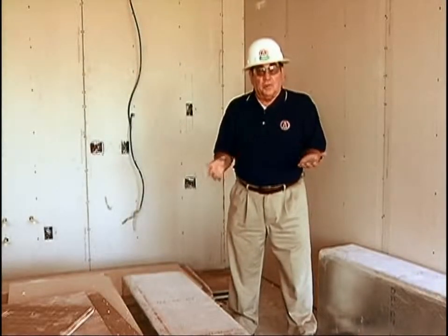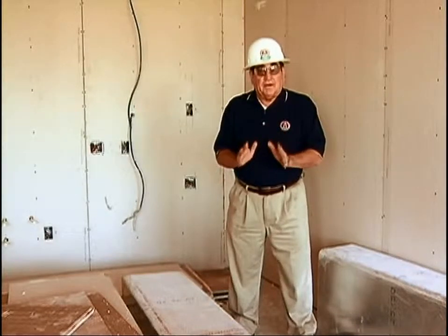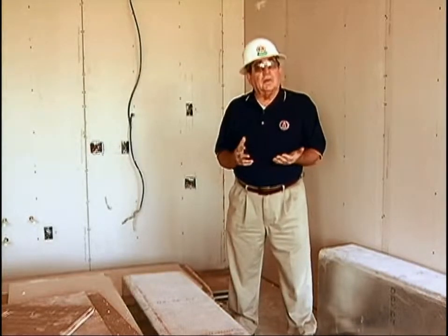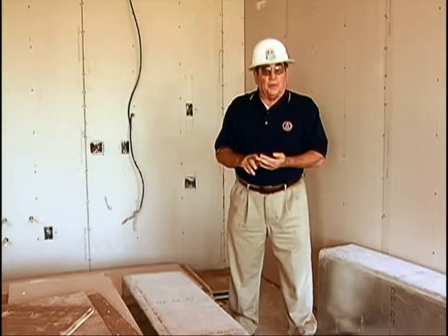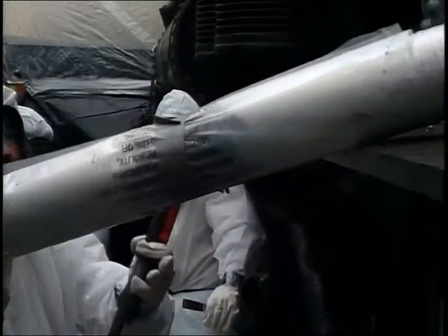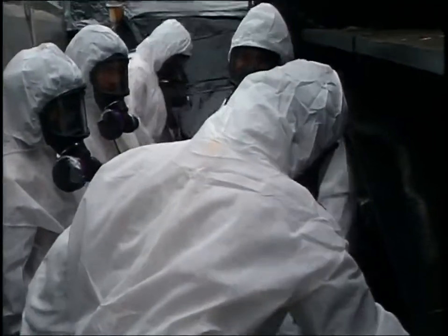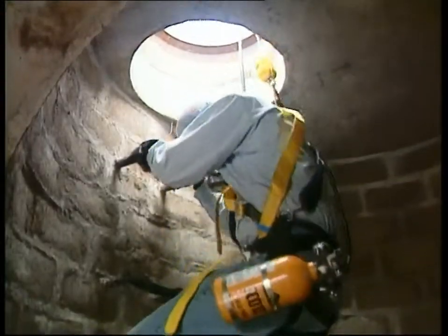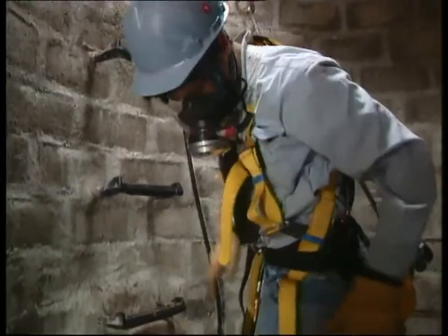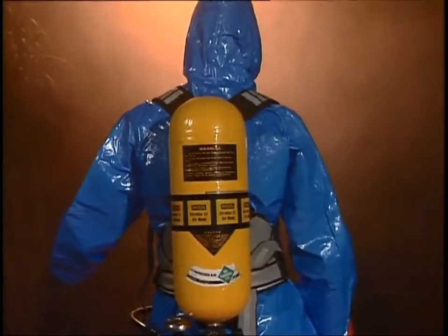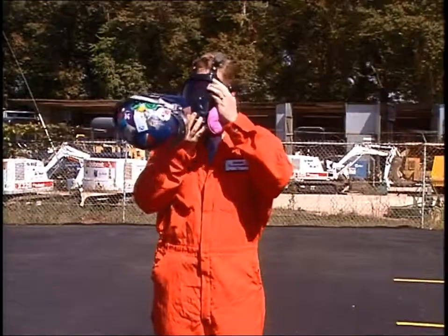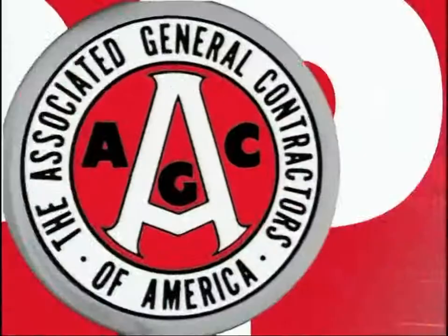Air contaminated with harmful dust, fogs, fumes, gases, smokes, sprays, or vapors can pose serious health hazards. Sometimes engineering controls are not feasible or fully effective. In such cases, workers must use appropriate respirators. A respirator is a protective facepiece, hood, or helmet that is designed to protect the wearer against a variety of harmful airborne agents. There are three main types of respirators: supplied air respirators, which provide pressurized breathing air; self-contained units that have air in a tank that you carry on your back; and air purifying respirators that use filters to clean the air you breathe.